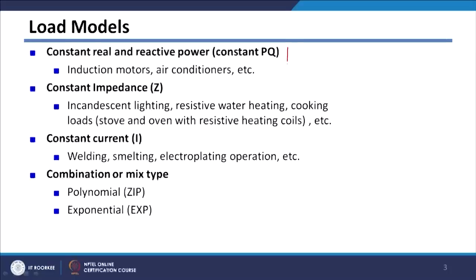Before going to the load models, first we will see why load models are required. If you know, while doing the load flow studies in your BTech class or undergraduate course of power system analysis, you might have used constant real and reactive power loads. That means in each iteration of your load flow studies, your power remains constant. The first load which I have shown here is nothing but your constant real and reactive power, that is called a constant PQ kind of load.